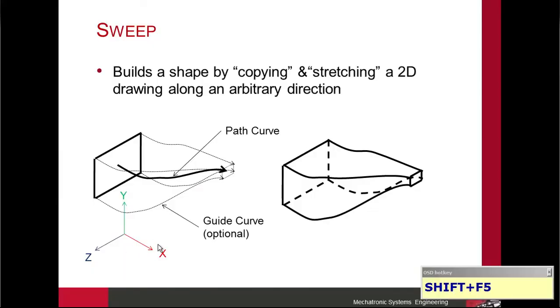Sweep is more generally used for a more complicated shape. So we can actually have this kind of the same shape. I can have it squished about like so, and then do all sorts of weird stuff. So that's where the sweep is actually useful. So when we are dealing with sweep, there are 3 curves you need to be aware of. The first one, I haven't labeled that, is known as the profile. This is the shape that is being swept or squished about.